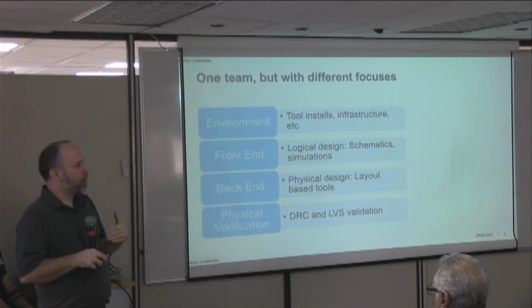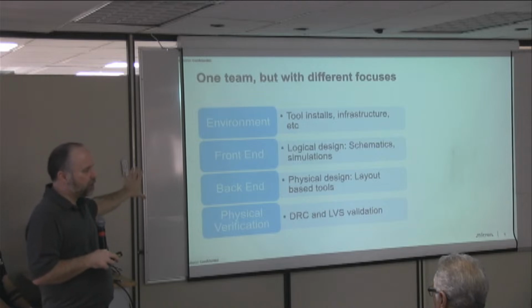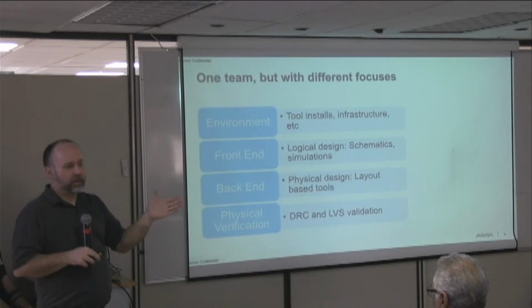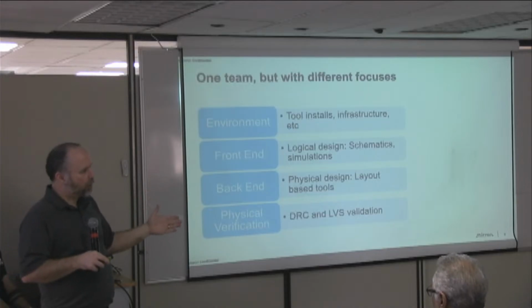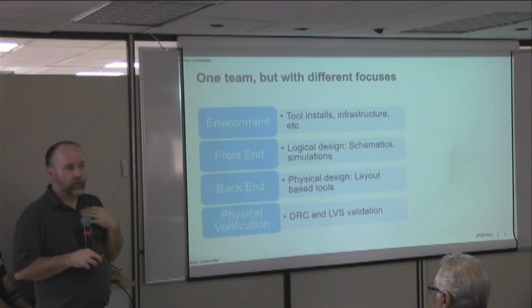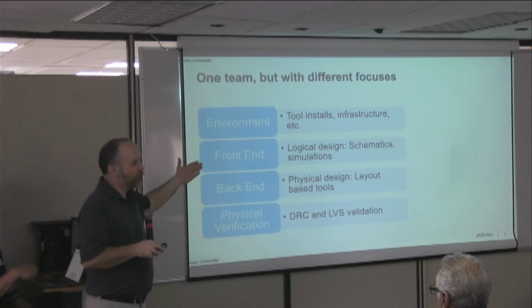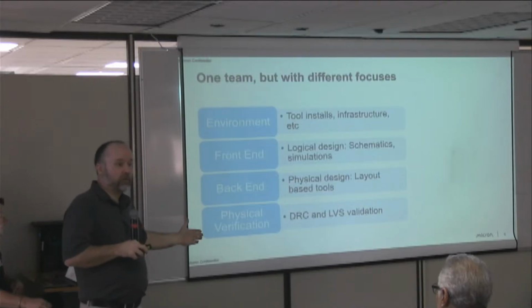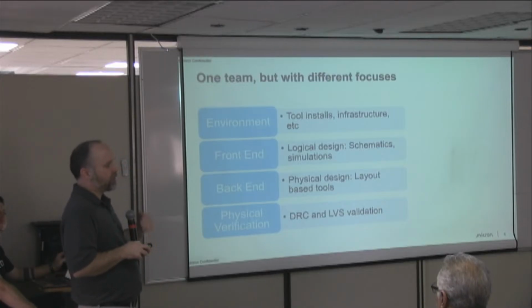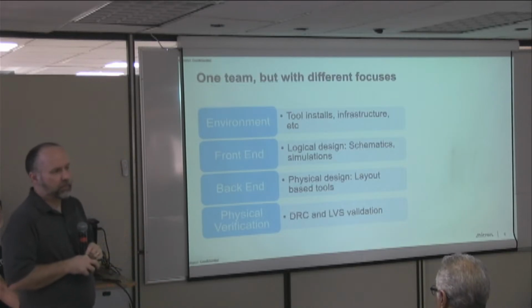And you look at a complex state-of-the-art foundry process, it might take 4 months for you to run that part through the fab. If you find out you have a problem, you not only have to buy a new reticle, you have to start over all that product, and all that product that you've been waiting months for is no good and it's garbage, right? And so that opportunity cost becomes a really big thing.